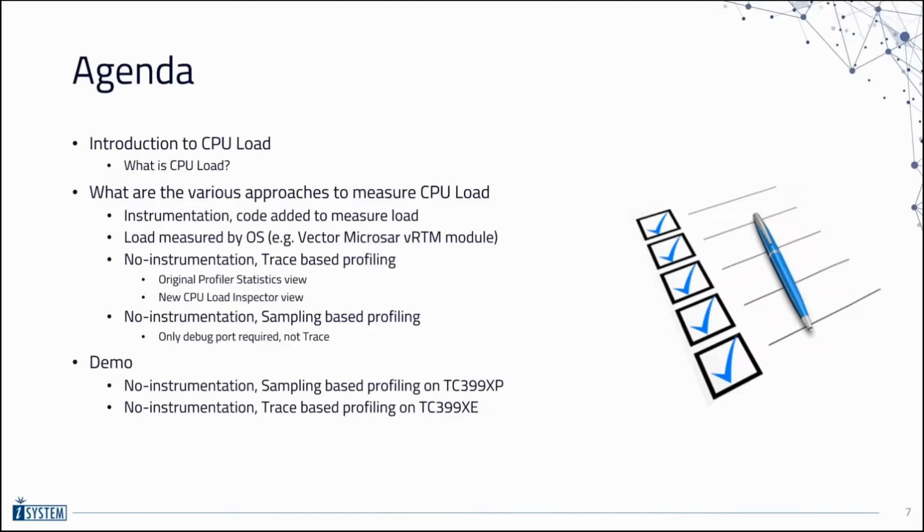Today's agenda will start with an introduction to CPU load, then we'll look at different methods to measure CPU load, 2 that require code instrumentation, and 2 that don't require any code instrumentation. Then I'll demonstrate the 2 non-instrumented profiling methods using a couple Infineon TC399 target boards.